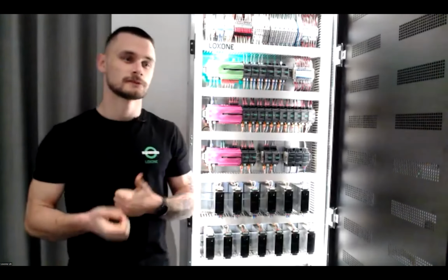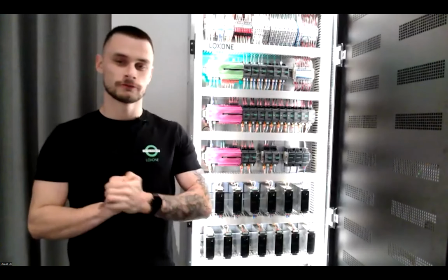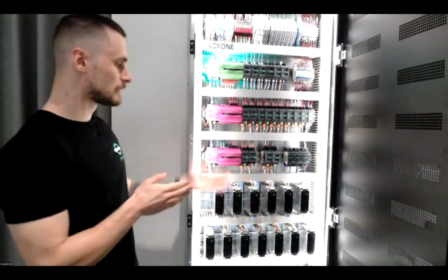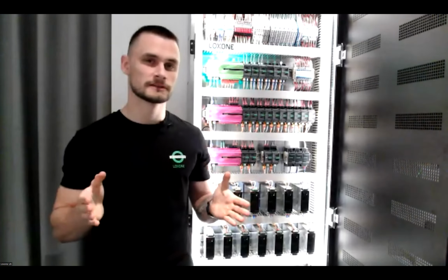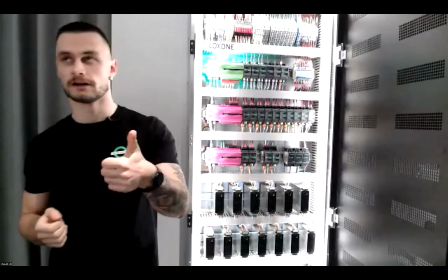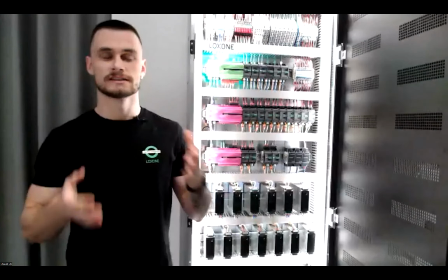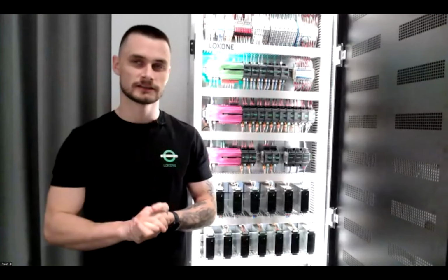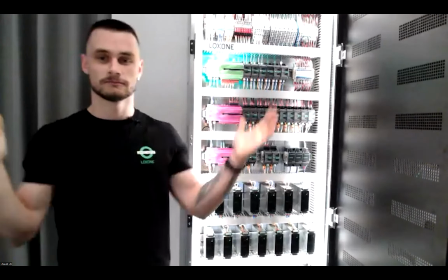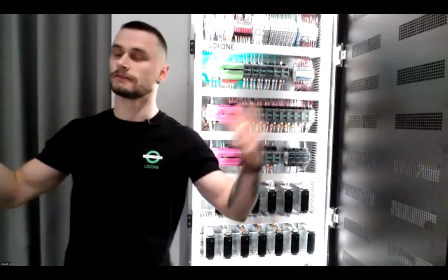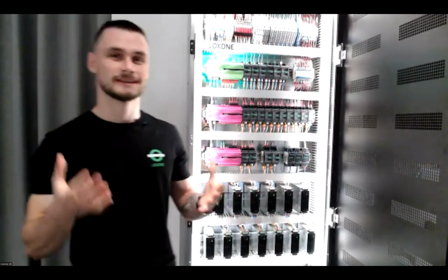So first of all, as you know, at least until config version 12.2, we were specifying in terms of power supplies at least 90% requirements, which means if, let's say, one spot is taking roughly 7.5 watts at 100% brightness, we're specing 90% of that, so maybe 7 watts per spot. If you have 10 spots in a project, 70 watts and so on. So we're going with about 90% total consumption.